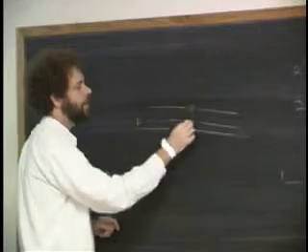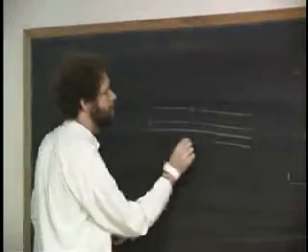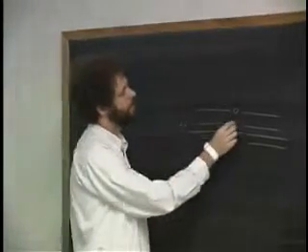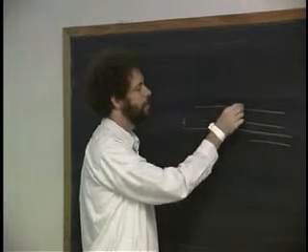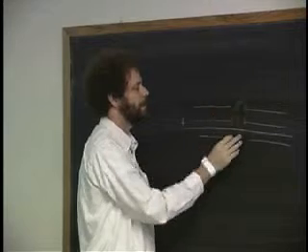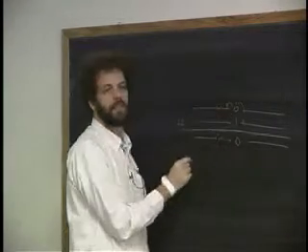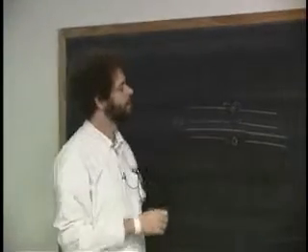Then the sum of 0 and 1 is going to be 1, right? And there's going to be other stuff here and other stuff there, except I need to be a little bit careful because it's possible that over here I had a sum, 1 and 1, let's say, which had a carry, of course, that came out of here. And so this is really 1 plus 0 plus 1, which is 0, and a carry got generated out of here. So this is nothing more than the binary version of adding numbers that you've known how to do since grade school.